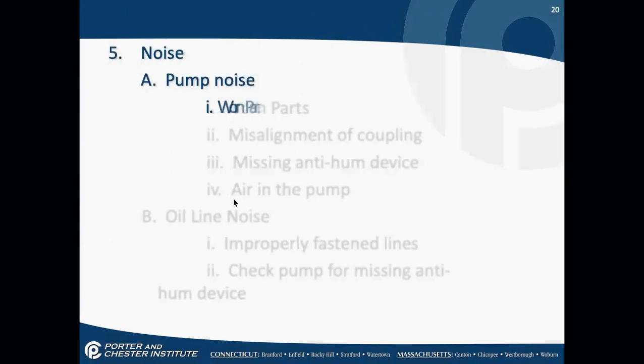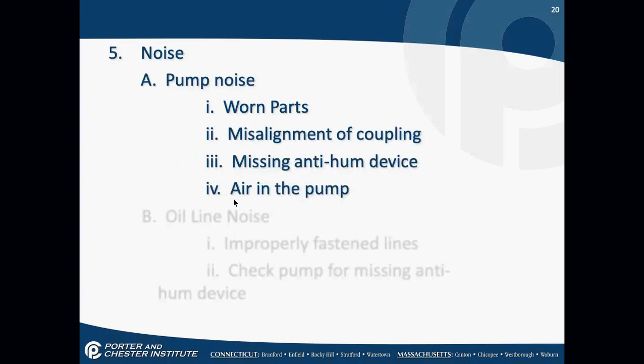Noise in pumps. If the oil pump is noisy, like whining or a little bit of a rattle, it's going to be a worn pump, worn parts. Could be a misalignment of the pump to the coupling. Could be a missing anti-hum device. Believe it or not, they have an anti-hum device on some of the pumps. But my biggest problem with noise in a pump is air. Bleed the pump before you do anything else.